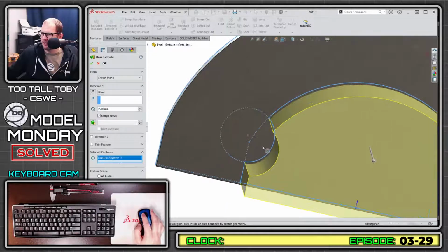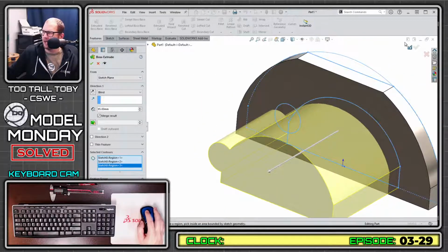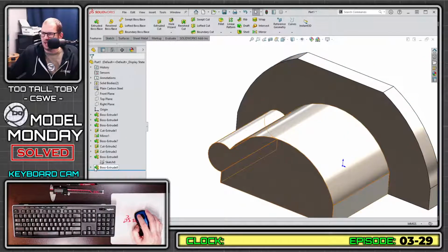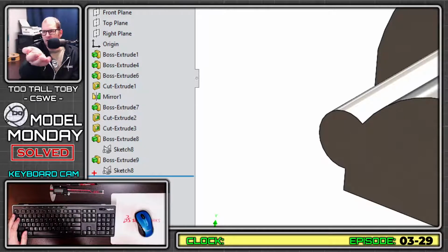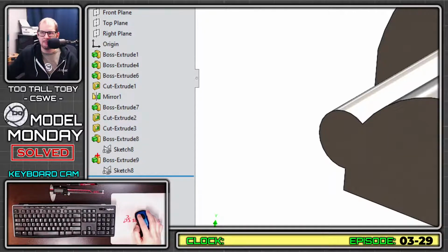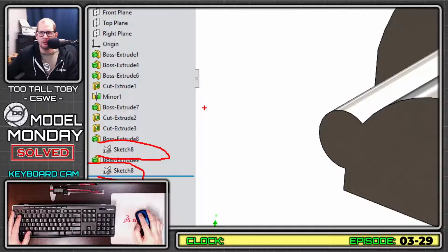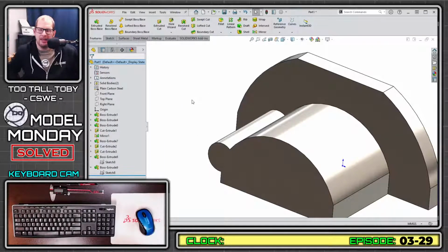And actually, I want this to come out with that, or maybe even this as well, right? We could just do that whole thing in one sketch. And that's what's called a shared sketch. It shows up in the tree here with a little hand underneath the sketch, like a Windows shared folder. So that's what's called a shared sketch, where you take one master layout sketch and then you share it out to multiple features. And that absolutely would work as well. Definitely a completely valid approach.